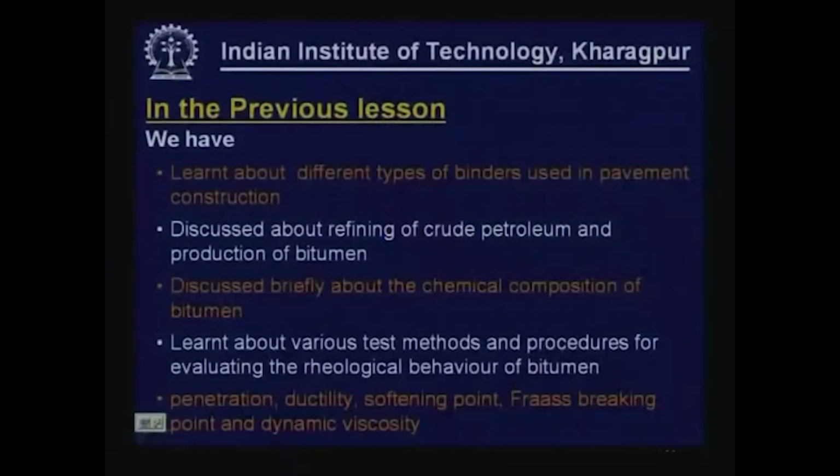We also discussed briefly about the chemical composition of bitumen, and we learnt about various methods that we adopt for testing the rheological behavior and other properties of bituminous binders. Some of the tests that we considered were penetration test, ductility test, softening point test, Fraass breaking point, dynamic viscosity.